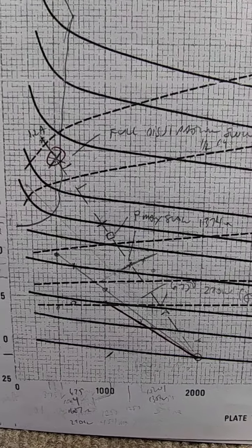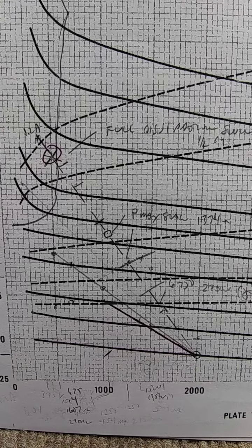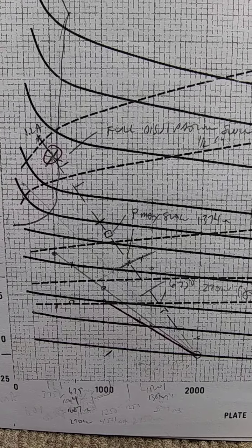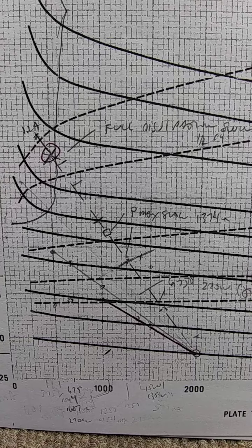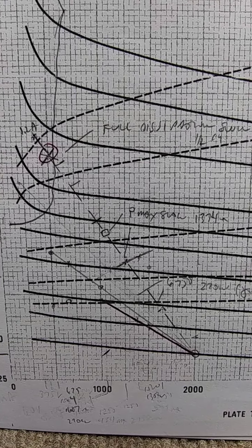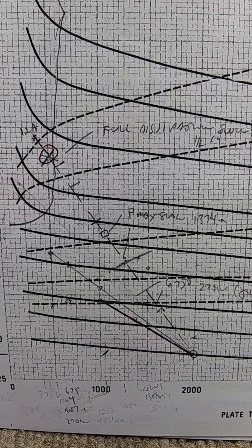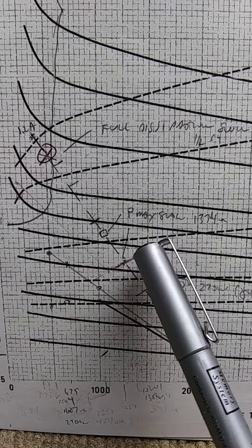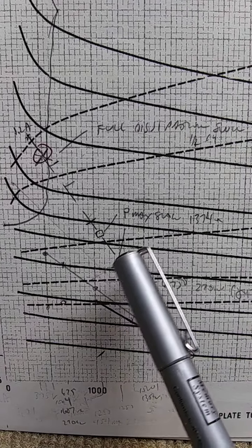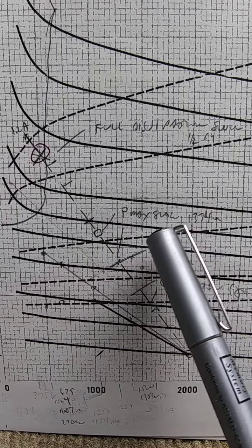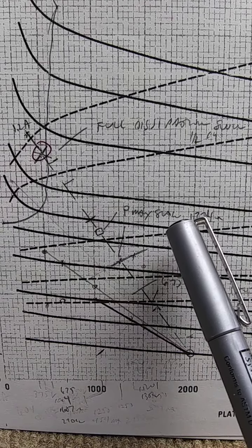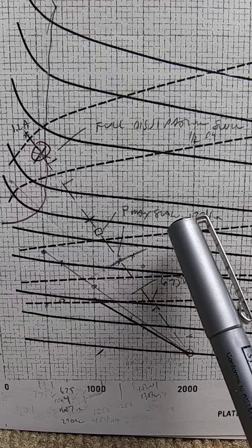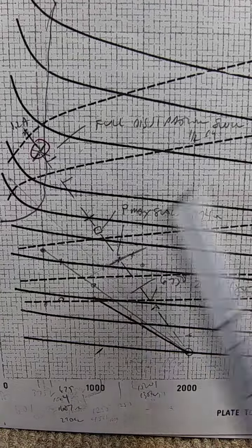That's kind of sort of ought to be obvious. I wanted to know where this plate resonant load resistance comes from, and a resistor can't be resonant. But where's that resistor at? Well, I plotted this line for 2750 ohms, which is the resonant plate resistance, or the resonant load resistance for the 2 kV minimum distortion case that I've been working with in these videos. That's that line.